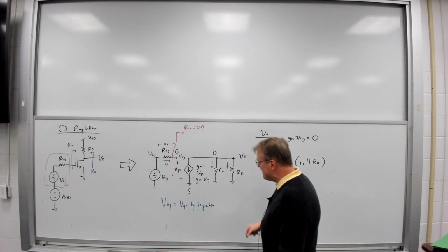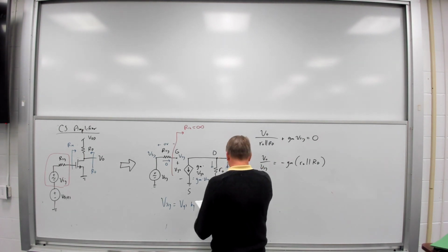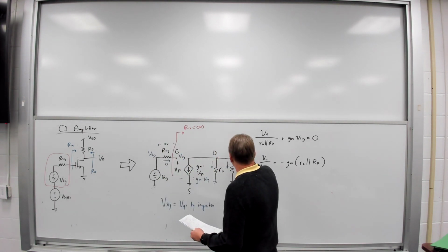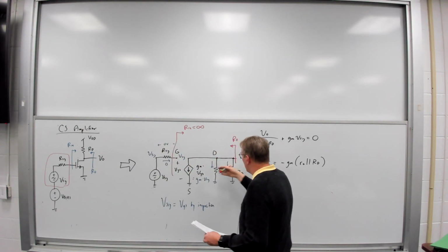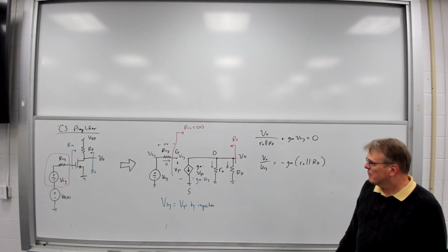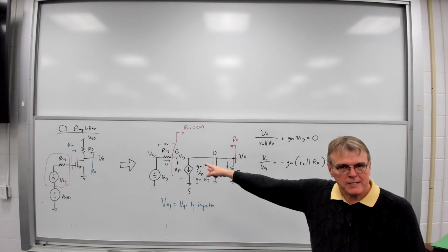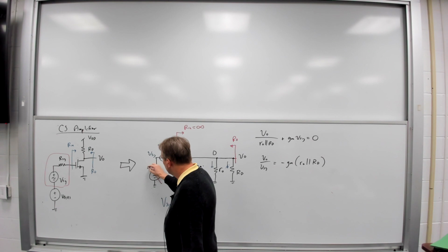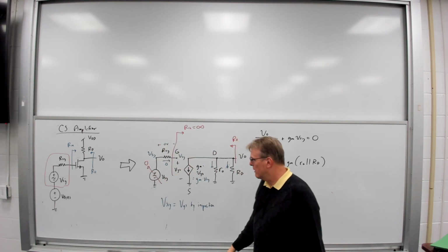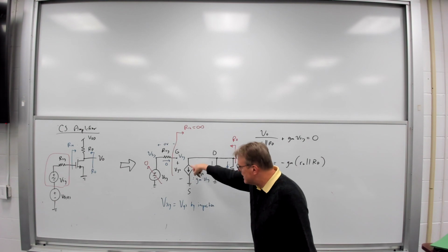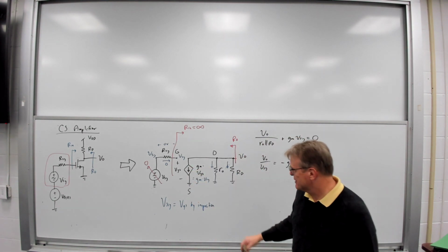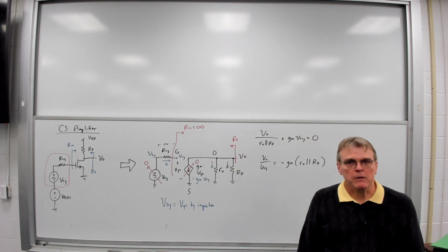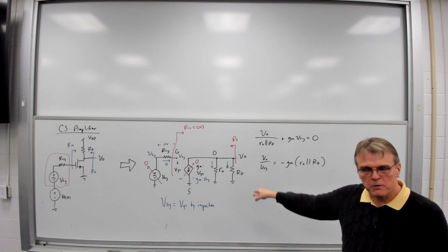What is the output resistance? Okay. Well, in this case, I'm looking back into here, so I'm going to be looking at R_o, seen looking back into that amplifier. So I'm going to have to use the source driving technique because I have dependent sources. What do I do? Well, I set this equal to 0. All independent sources in the circuit go to 0. If that goes to 0, what happens to that dependent current source? Also goes to 0. And therefore, what is my output resistance going to be equal to? r_o in parallel with R_D.